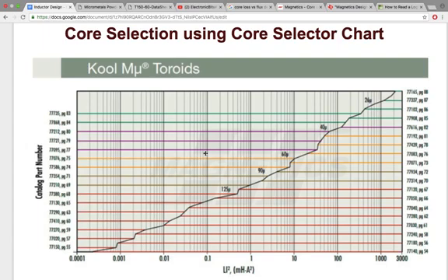We know the inductance value and its current requirement, so we can find L I square, which is proportional to the magnetic energy. Basically, it's the amount of energy you want the core to handle. Using that, you can find what energy the core needs to handle.